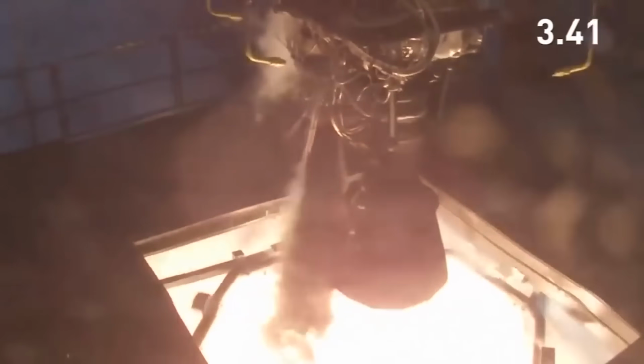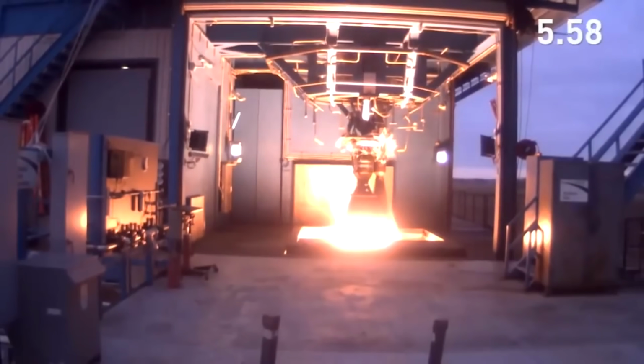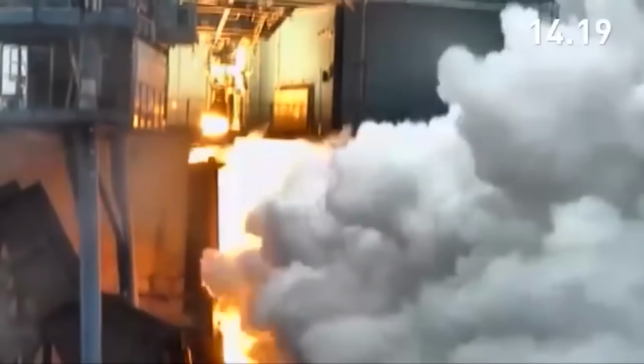With a gas generator, all the exhaust gases that were used to spin the turbine are simply dumped overboard, or perhaps used to cool portions of the nozzle, but the gases are not added into the main combustion chamber. That's why this is called open cycle. The exhaust gas is used and then it's expelled to the open air or space. It's not used in any part of the main combustion process.